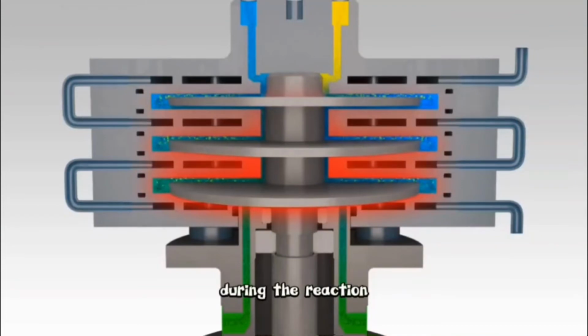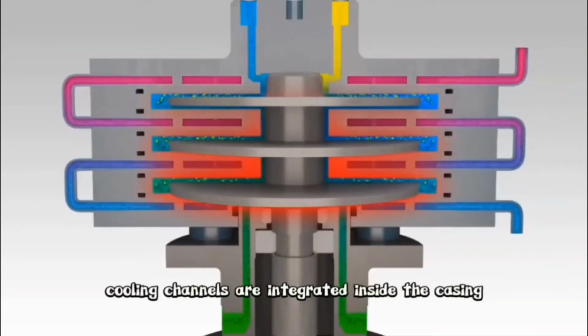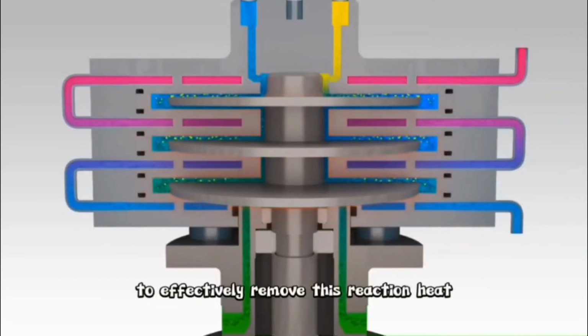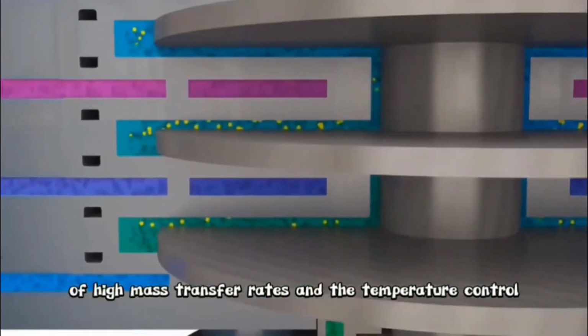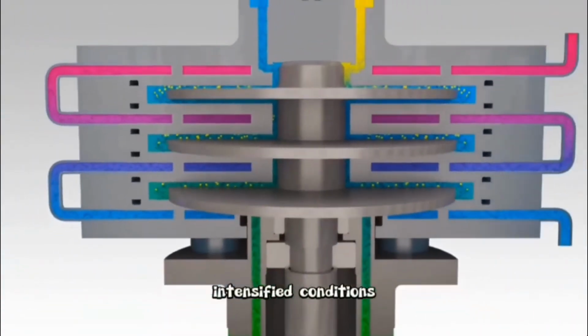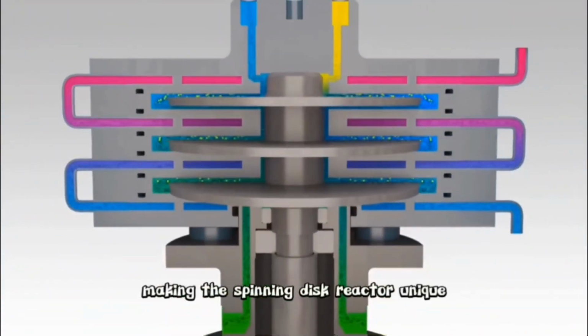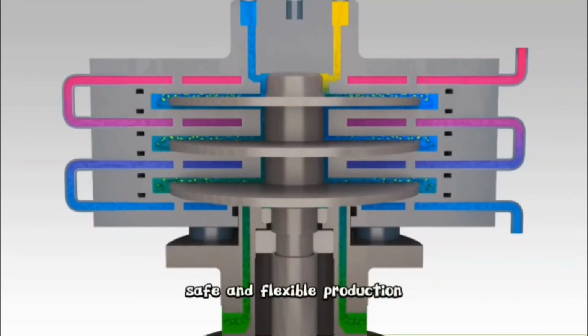During the reaction, large amounts of heat are released. Cooling channels are integrated inside the casing to effectively remove this reaction heat. The combination of high mass transfer rates and the temperature control allows reactions to proceed under process-intensified conditions, making the spinning disc reactor unique in terms of efficient, safe and flexible production.